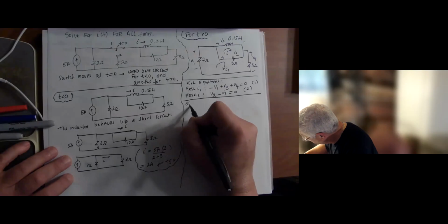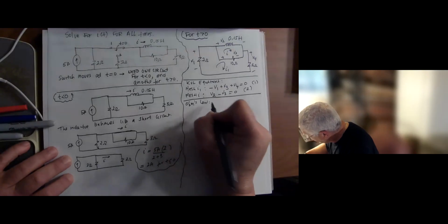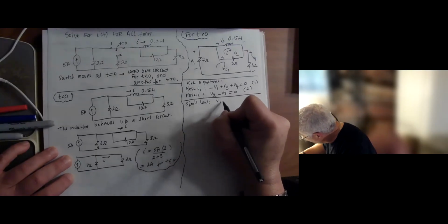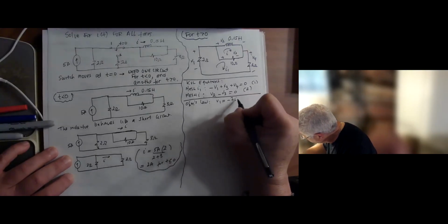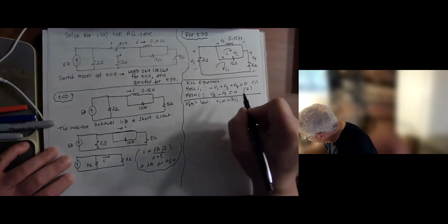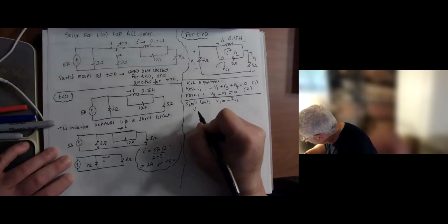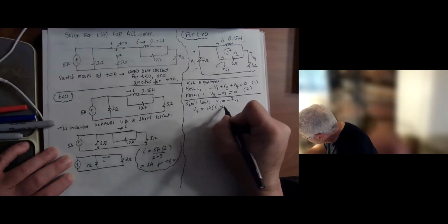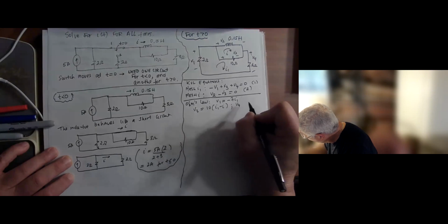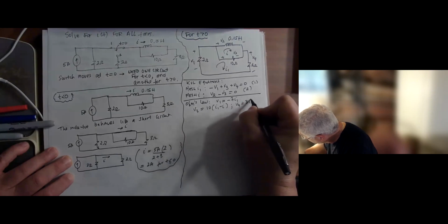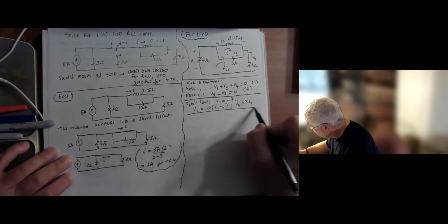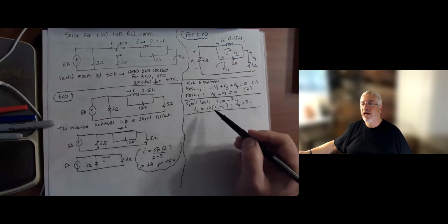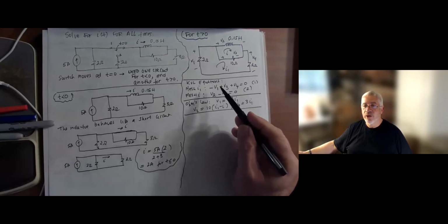Then we go to Ohm's law. Again, for the time being, realize I'm leaving the inductor alone. Ohm's law meaning what? V1 is equal to minus 7I1, passive sign convention. Then I have V3 equal to 10 times (I1 minus I). And finally, V4 equal to 3 times I1. You see me putting these lines because I want to separate the major components of the mesh procedure for you. KVL equations,